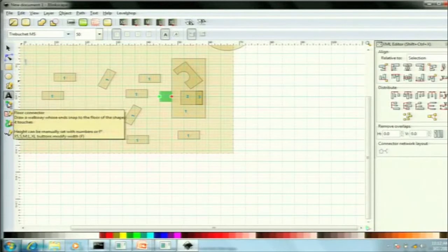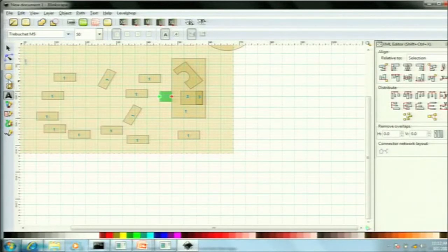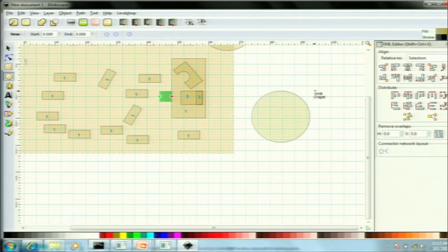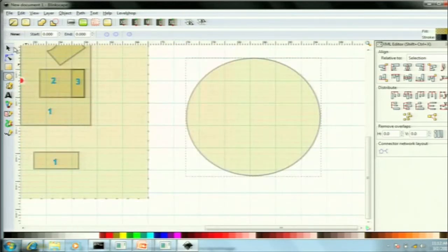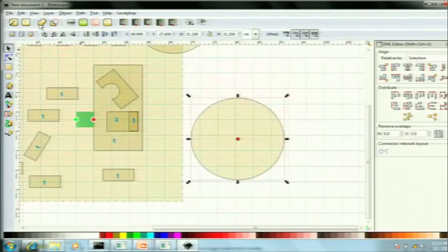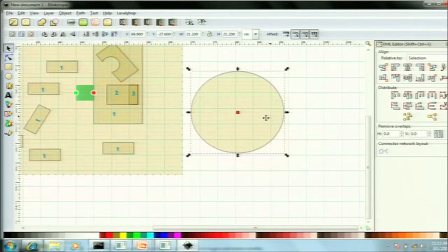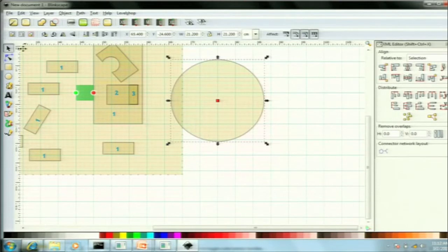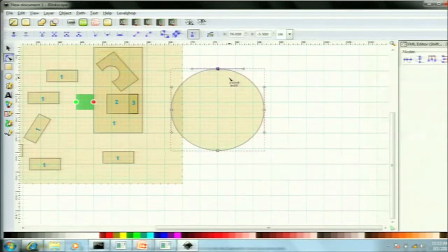So let's take this. Haven't done a spiral in a while. So this is a little bit of a trick. This is level 301. Okay? So I apologize to all those people who want to stay at level 101. So we take this. I'm going to go into sub-object mode. I'm going to select that and let's see, join, split the path.